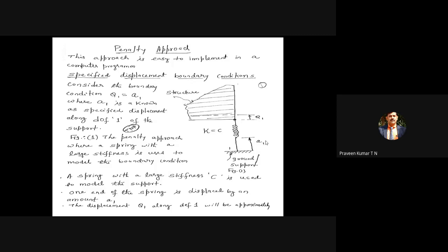Suppose instead of plastic wire, you mount it rigidly. Plastic wire has very low stiffness. Finite element packages will not understand these notations. They will understand boundary conditions only when each and every boundary condition is written in equation form.